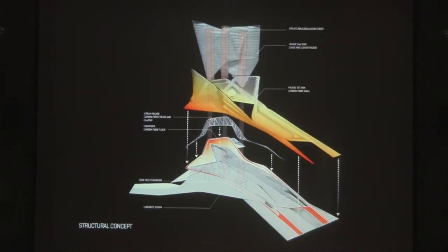And that gradient condition we begin also looking at. We're working with Bureau Happold in Los Angeles here. Some of you may remember Greg Otto from USC, who's the principal of Bureau Happold. And this is the structural analysis of our geometry from Bureau Happold off of what we were hoping to achieve, which was 3 concrete cores which support these slabs, and then a perimeter exoskeleton, which is actually not a skeleton, it's a skin structure that becomes a grid structure. So there is a gradient condition.